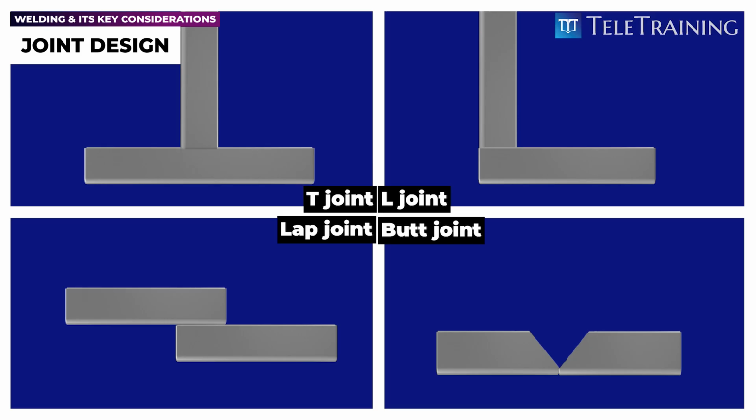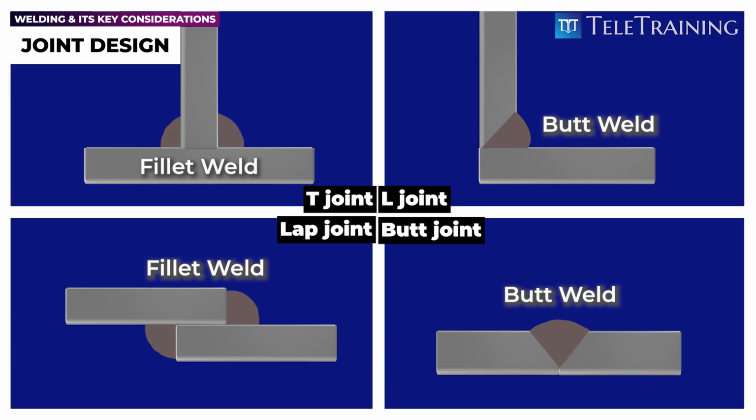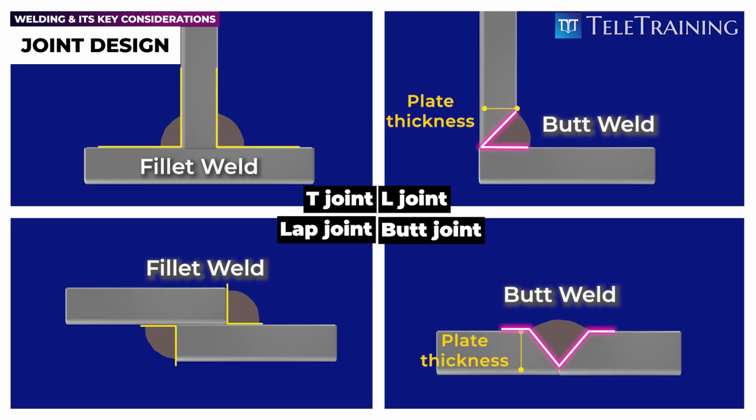There are mainly 2 weld types: butt weld and fillet weld. Butt welds run the weld metal within the thickness of the plates. So, special joint preparation, like a butt or V-joint, is required before welding starts. While fillet weld is simply run along the outside of the plates. So, no special joint preparation is required, as the weld can run on the outside face of a T or lap joint as shown.